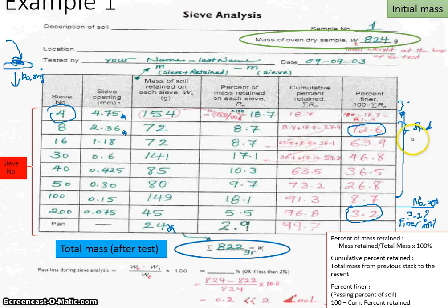So only 72.6 minus 3.2%, it will be 69% sand, and 100 minus 81.3 is gravel. If we total up, it will be about 20% here, 70% here, and less than 5% here. So the total will be 100% again. So that's how we check the sieve analysis.